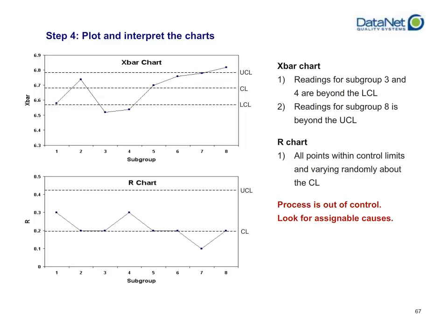In each one of those 3 cases where you fell outside of control, you should have tried to investigate had you been plotting this in real time. And you would have been able to plot this in real time had you some data, enough data historically to actually go in and begin plotting this. This is where WinSPC comes into play. You would have been able to catch these out of controls immediately and begin to investigate and determine if it was in fact a true positive or a false positive.